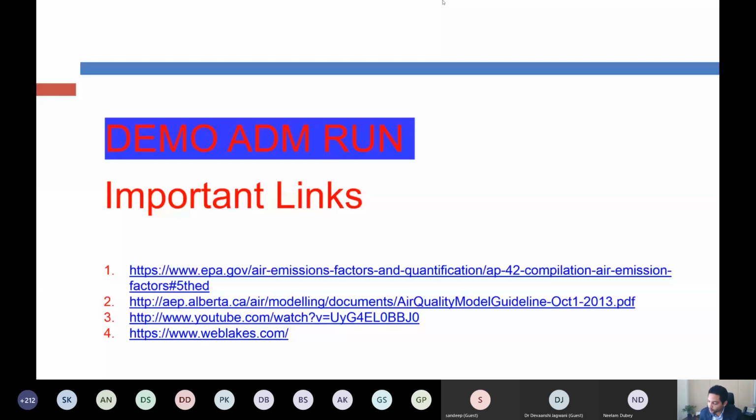And when we come to question two, what are the equipment? When we see the traditional equipment used for PM, particulate matter, in India specifically, there is equipment manufactured by Envirotech and Ecotech and others, which uses a high volume sampler. The principle is to measure dust levels by the gravimetric method, in which one piece of filter paper is used, and there's a pump in the equipment which runs for the period that we want to measure, 24 hours or 48 hours, depending upon the duration. Then the dust collected on this filter is weighed, and the concentration of particulates is calculated.